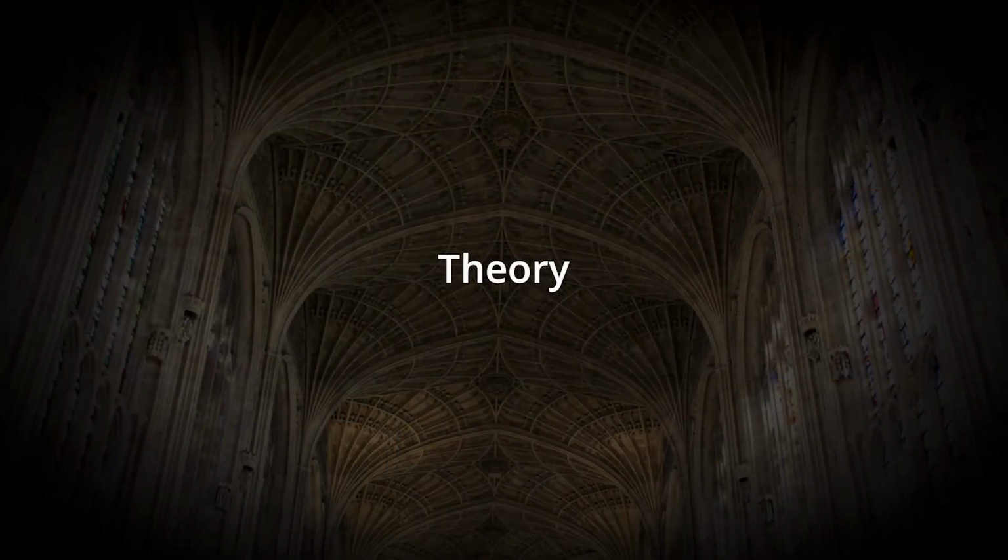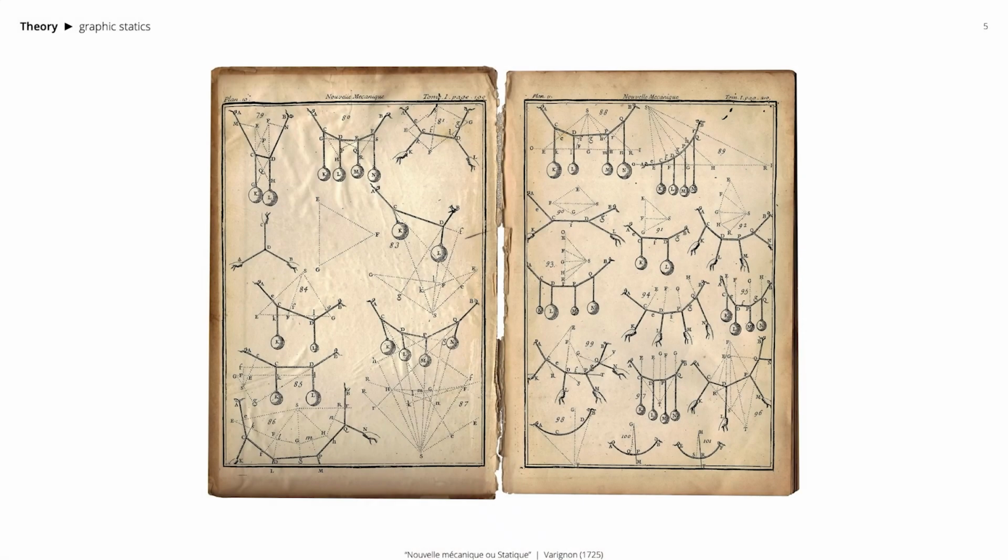First, I would like to begin this introduction video for RhinoVAULT 2 by presenting some of the core theoretical principles and background information on the thrust network analysis, which is a graphic statics-based form-finding method that RhinoVAULT 2 is based on. Graphic statics is a design and analysis method for two-dimensional discrete structures that relies on geometrical rather than analytical or numerical representations of the relation between a structure's geometry and the equilibrium of its internal forces.